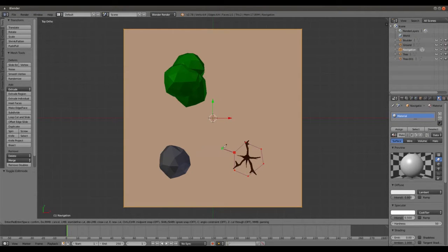So just kind of cut around it like so. And alright, you can see what it did, and this is actually pretty important. It made the vertices connect to the corners that were already there. Like the cut tool will before, except for the vertices you create by making cuts, it will try to connect to vertices that are already there. And that's very important because in navigation meshes we want the vertices only to be at the exact corners, because that makes a difference.